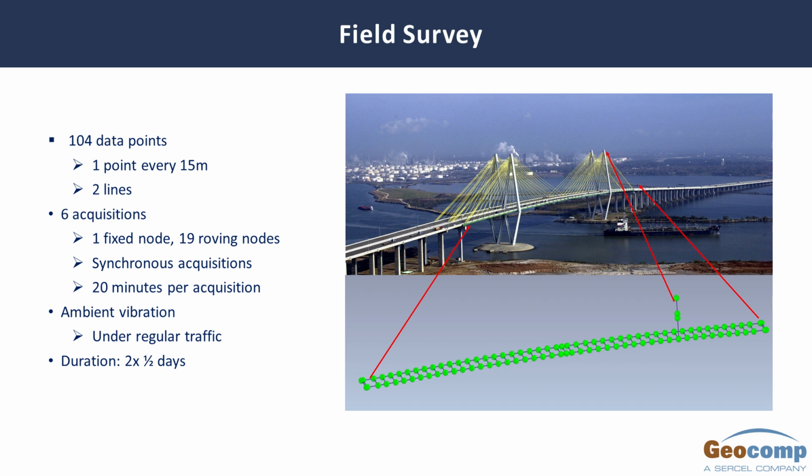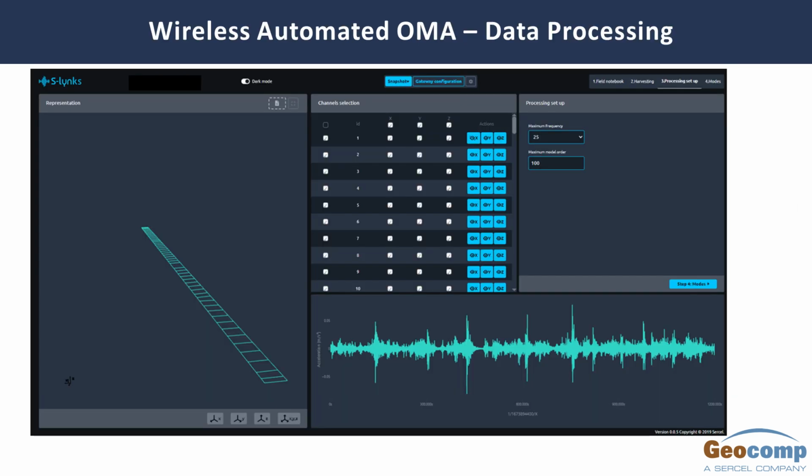Simultaneously, as you are doing the study, you build your geometry and then upload your data to the cloud, where we run our sophisticated algorithms to break down the mode shapes, basically. So this is the result from Fred Hartman Bridge. As you can see, almost all the critical frequencies are within the 0 to 1 hertz range.